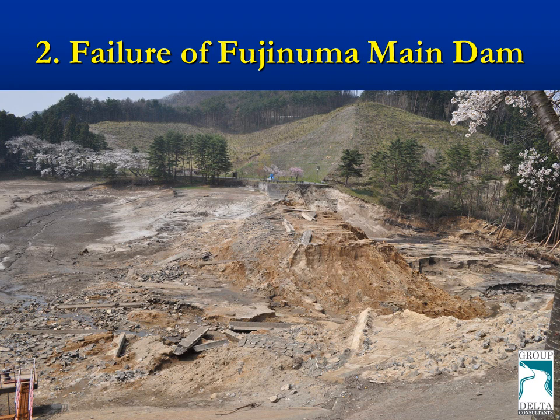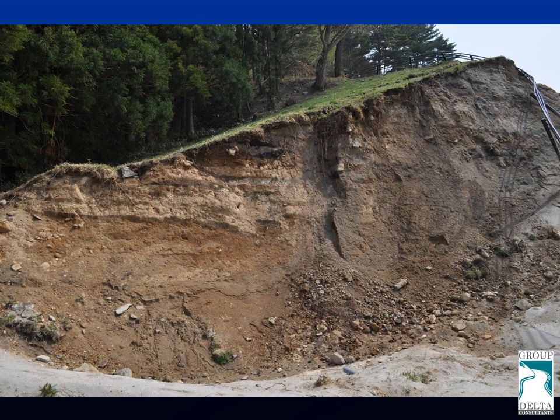When I visited the site in April of last year as part of an ASCE reconnaissance team, the dam was completely destroyed and also had a bridge near the right abutment that had been carved by the flow of water. One of the key observations made during the site inspection was that the dam was made mainly of cohesive materials that stood up to relatively high heights without any need for support.